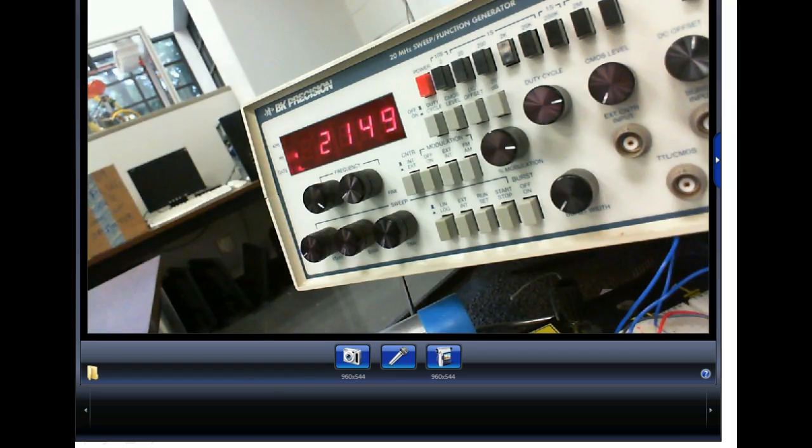Be careful with the what? Polarity. The video I showed y'all the other night. By the way, I did put that up on Blackboard. So capacitors are rated in two things. What are the two things they're rated? Farads and voltage. Farads is their storage capacity. So the bigger the capacitor, the better the filter it is.